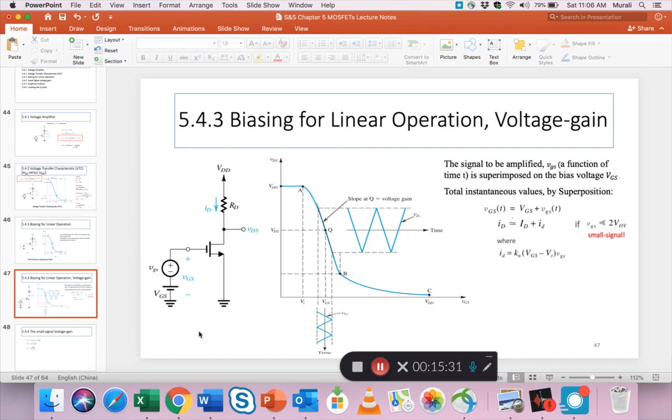But remember, to be able to do that, your circuit has to satisfy the condition of linearity. That means if it is only a resistive circuit, it's always linear. But once you have these devices like diodes and BJTs, linearity is only possible with certain conditions. Some combination of currents and voltages only give you linearity.